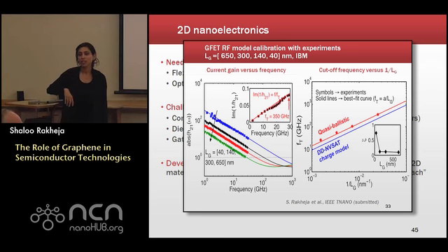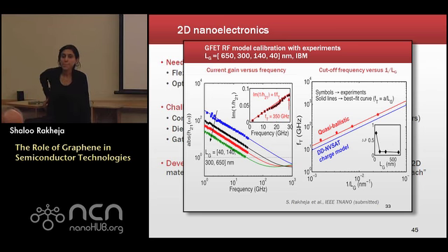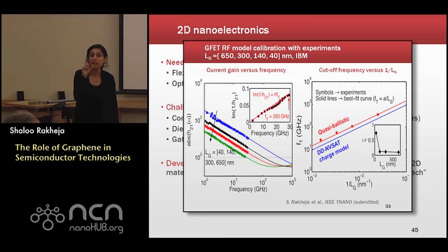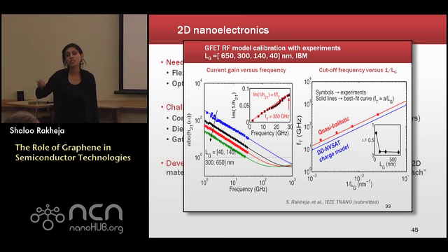Yeah, but could you, for example, say you push the Fermi level from 0 to below 0? So this asymmetry comes from that change in the potential barrier height at the contact. If you want to understand that very clearly, you have to see how the potential profile changes underneath the contact and how it keeps changing in the channel. So that change is different for electrons and holes.